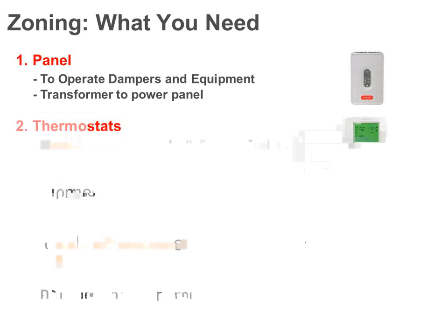All right, so the way you decide to zone the house is different for every project depending on what the homeowner wants, but you got to divide the house into zones. There are numerous things that are going to dictate how this thing gets divided, right? There's the perfect scenario, which means you divide it up based on how the homeowner wants to be comfortable in different rooms. And then there's the realistic example, right, which is, well, what ductwork can I get to in this existing house, and where can I jam a damper in, and where can I not do it? So you're going to end up having some compromise of the number of zones and the zones that are grouped together. We'll talk about how to do that here.